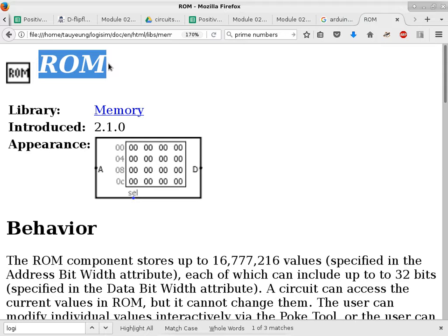The next generation adds another E to it. So we have double E PROM. So double E PROM, the first E stands for electrically. So it is electrically erasable, programmable, read-only memory. So with those chips, it is just a regular chip. Okay, there's no optical window anymore. To erase the content, you have to put it onto a special programmer board where they use a different voltage to erase the current content so they can be programmed again. Okay? Is that okay?